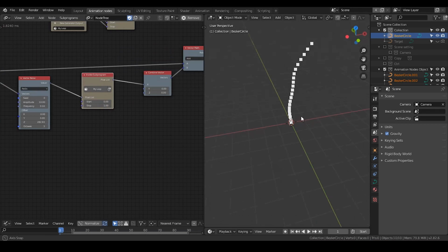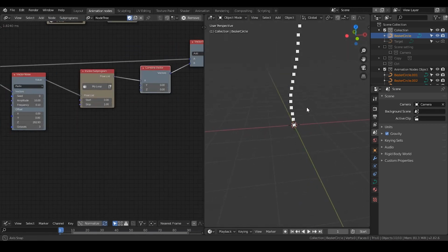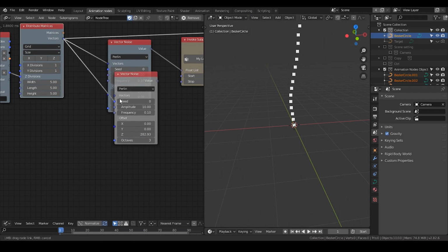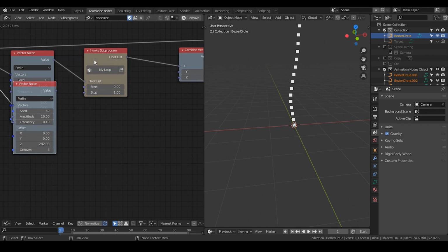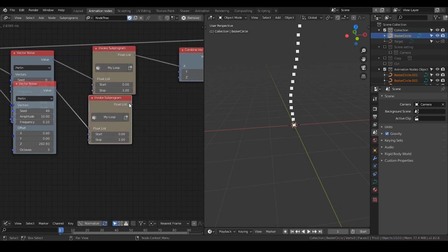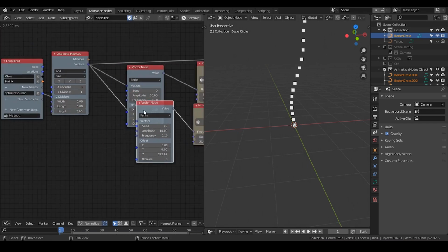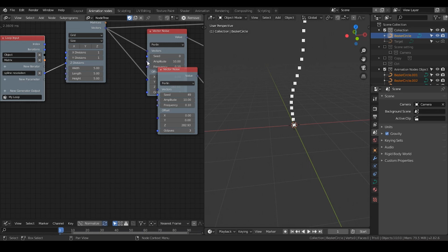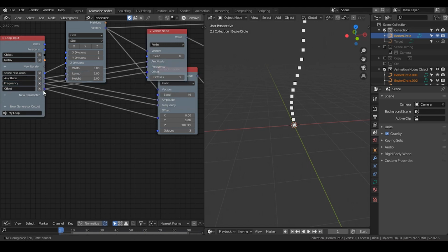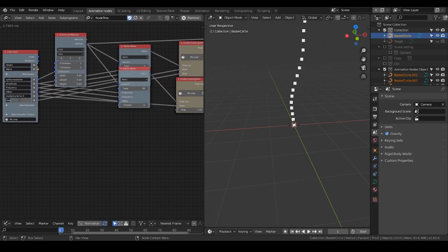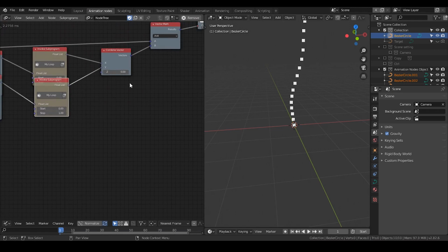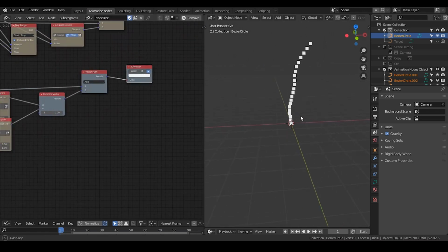But now we're only working with X. I also want to work with Y, but not Z. So let's just do another vector noise. Put the vector into it, and I'm going to change the seed and duplicate this loop. Put the float math into Y. Just remember, if you would like to procedurally change all these parameters in other places, like at the beginning of this loop, put everything into the parameter, like the amplitude, frequency. No, I think I'll probably not change the start and the stop because we have amplitude already to change. Okay, so now this is done.